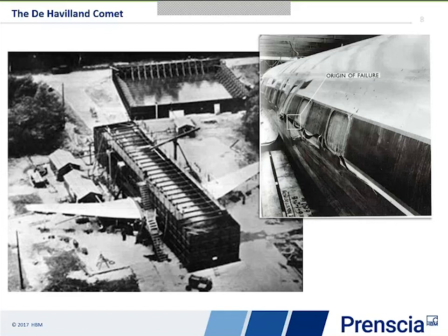So based on a factor of safety of about 3 for fatigue, which was thought appropriate at the time, the fatigue life of the aircraft was put somewhere between 1,000 and 9,000 flights. And actually, when we look at the first aircraft, it failed not long after that number of flights.